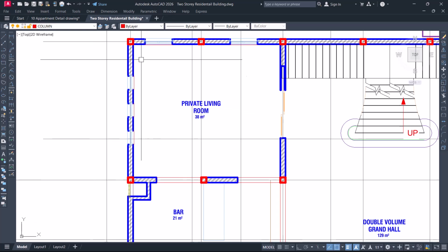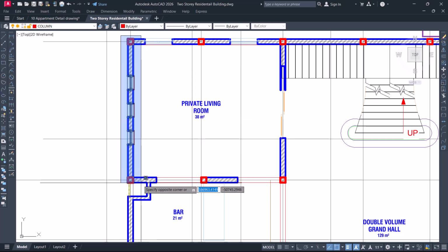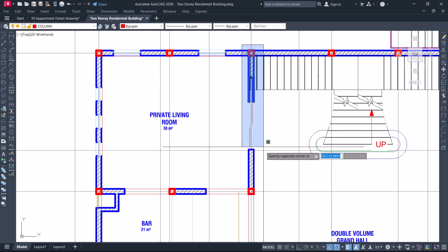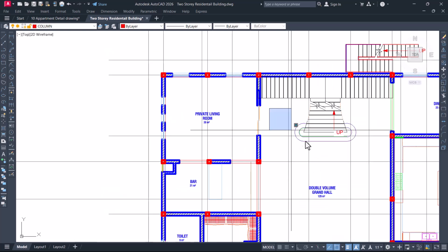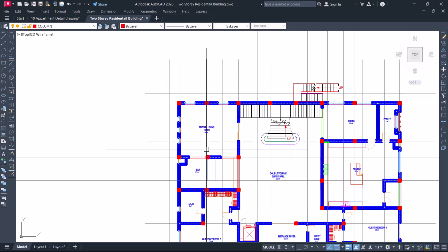Just that the reinforcement for this beam at minimum will be 4 diameter 16 downward. There may be 3 up or 2 up. Then this one here, since it's having slab only on one side, because here is a void, a double volume, they will still have the same reinforcement. This and this will have similar reinforcements. Okay, 4Y16 maximum, and then 2 or 3 up.